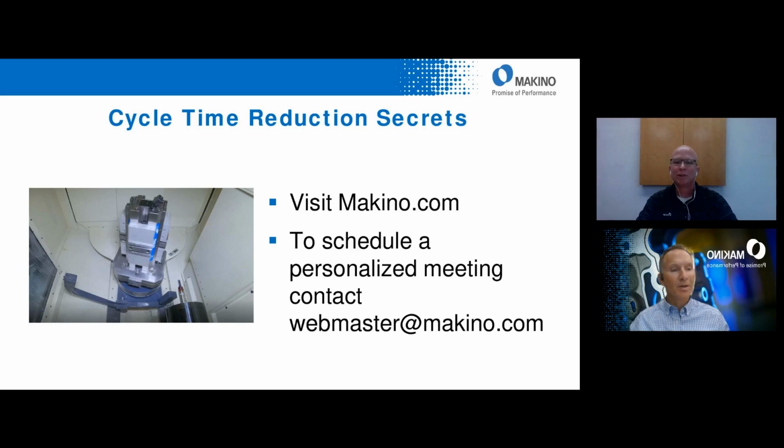Okay. Yep. Okay, and one of the other parts of the demonstration you were showing us, Mike, had to do with starting and ending closest to the tool changer and the cycle time savings you can get just from doing that. Here's a question that is related to that. It says, if there is only one part on the fixture, is it worth programming features nearest the ATC first on that single part? So I guess the idea being, you were showing us a demonstration of, say, 2 parts up where you have a part on each side of the fixture. But this question is, hey, I've only got one part. Should I worry about the features that are maybe closest to the ATC versus features on that part furthest away?